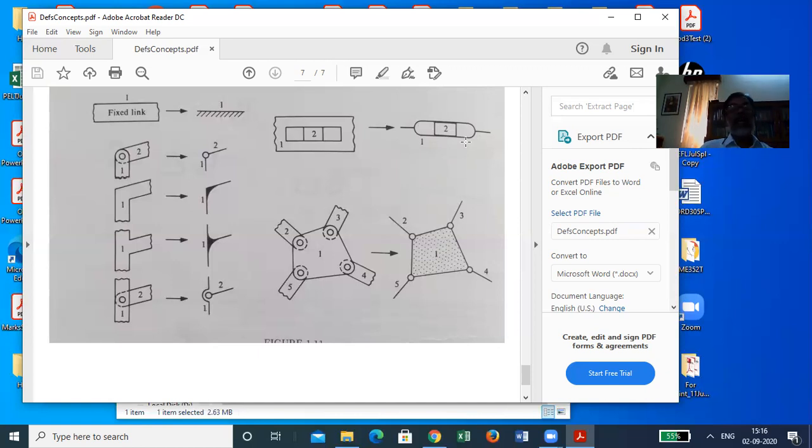Now this is something important which you do for ternary, quaternary, and higher connection links. You do not simply make the polygonal kind of representation with little circular joints. You put some shading, either dots or hatching inside, to show that all these four corners, the entire body is rigidly connected, it is part of the same link.